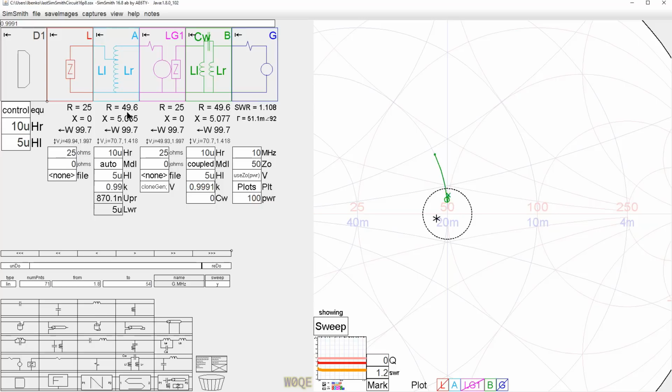1% of the flux was lost in this transformer. The 1% didn't couple, so it just went out in the air. So 1% of it didn't couple. In this case, 0.09%. That is like 11 or 12 times as much flux could be lost in this transformer versus this transformer.